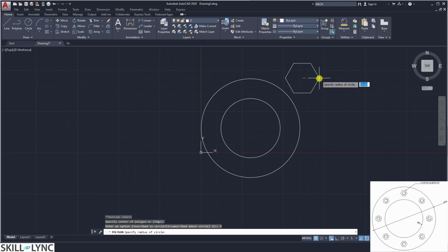So let us quickly draw one hexagonal bolt like this and look into the terminologies. Typically this face and this face is called across flats, wherein you put in your wrench to tighten the nuts, whereas this edge from this to this is called across corners. So these are the two terminologies that you can describe the hexagonal bolt or nut.